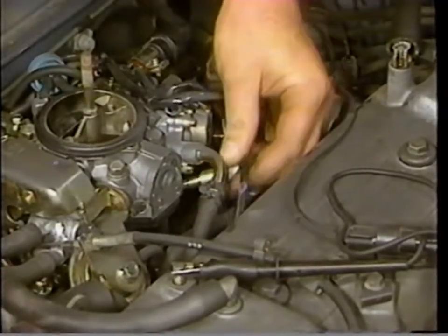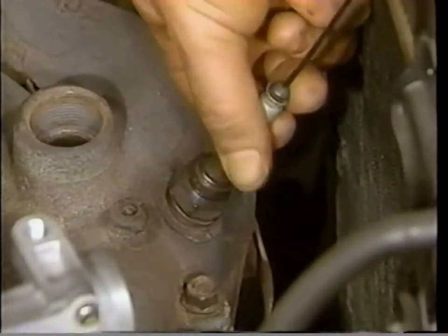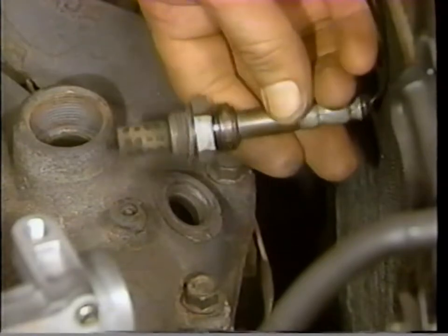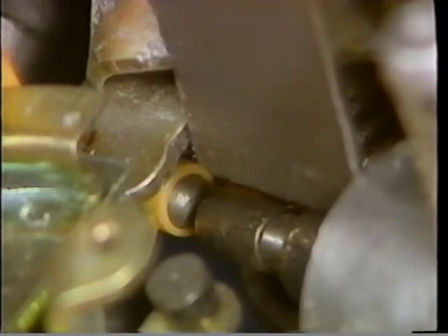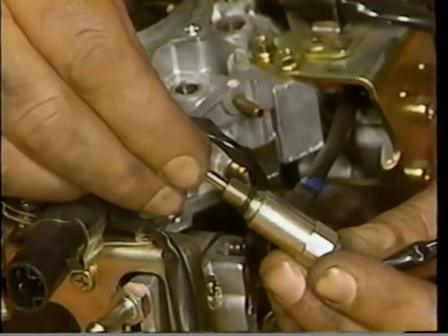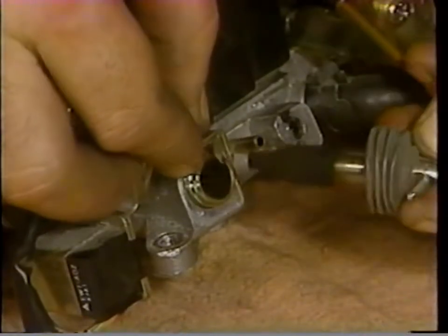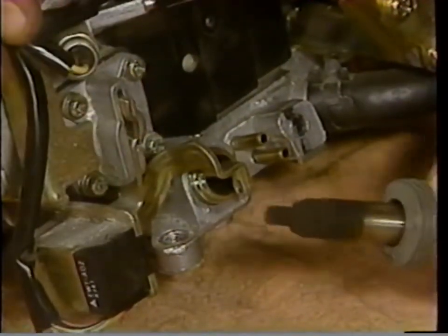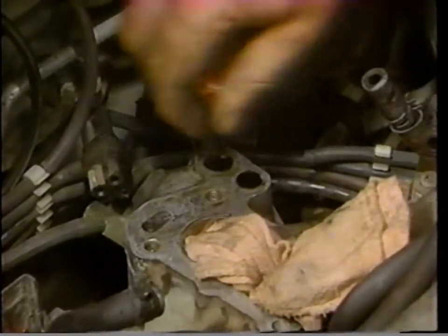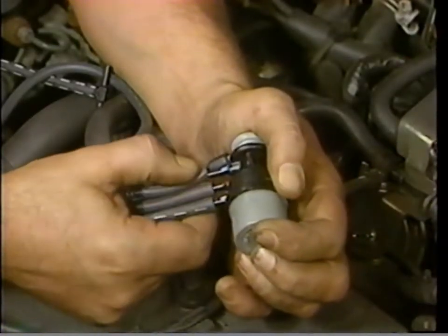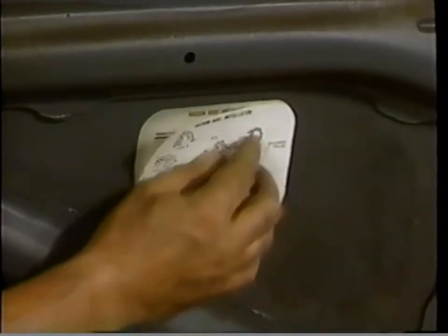The jet mixture solenoid must be inspected and replaced if necessary. The oxygen sensor must be inspected and replaced if necessary. A carburetor choke adjustment shim must be installed. The enrichment solenoid jet must be replaced. The sub-EGR valve and passages must be cleaned. The EGR valve and passages must be cleaned. A vacuum hose harness must be installed, and a hose routing label must be installed.